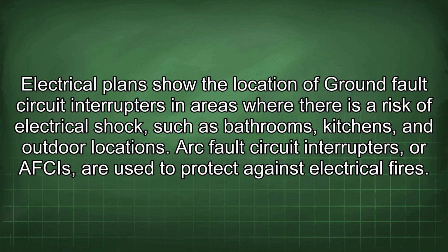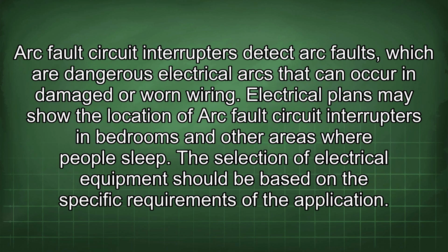Arc fault circuit interrupters, or AFCIs, are used to protect against electrical fires. Arc fault circuit interrupters detect arc faults, which are dangerous electrical arcs that can occur in damaged or worn wiring. Electrical plans may show the location of arc fault circuit interrupters in bedrooms and other areas where people sleep.